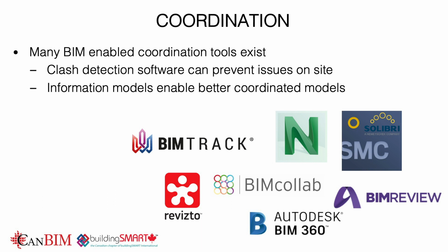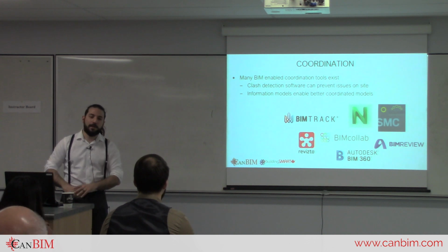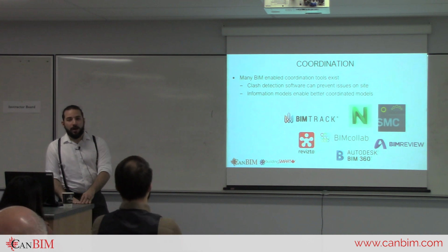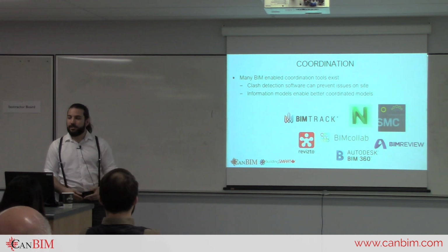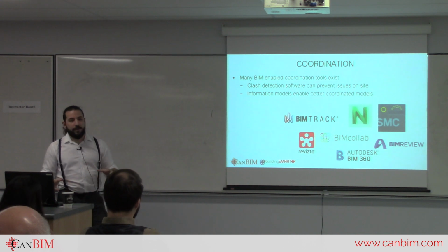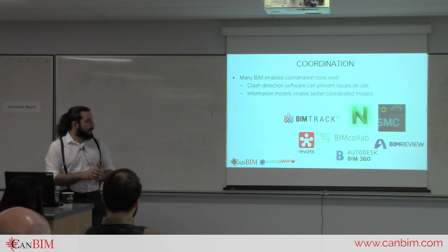Besides the clash detection software, just keep in mind that coordination is not clash detection. Clash detection is coordination, but coordination is a broader term. If I had a column in front of that door, that's not a clash, but it's also not great design. So that needs to be coordinated. And we have software that allows us to do this a bit better, I think.